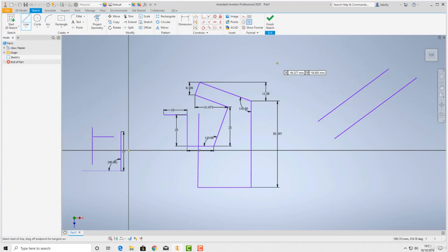Okay, if I did a line from there, well actually this line was supposed to start on that line. I misclicked, or I didn't zoom in enough, something. I did it by eye, but it was actually supposed to start on there. Well, that's fine. Coincident constraint. First point, you click on the end of the line because you need to tell it which end of the line is on there. So you can see when you go over the end, you get the green point. So that point needs to be on that line and there. So now it's coincident. Still could be any angle, but it is going to finish. Then those two lines are going to touch, okay?